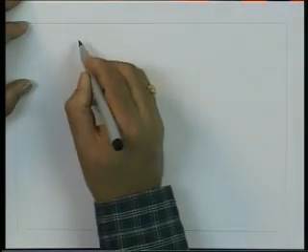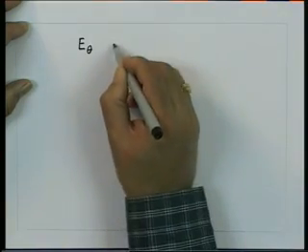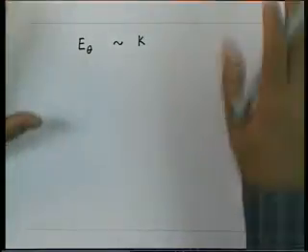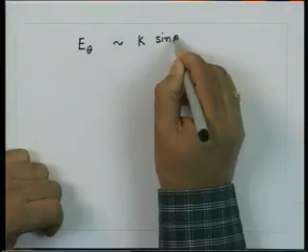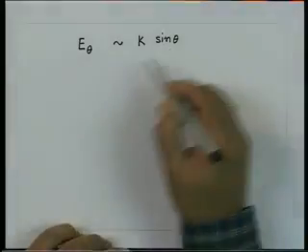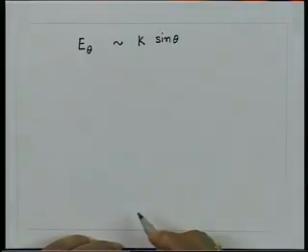So essentially we have a variation for the electric field, E theta, that varies as some constant, which includes all those factors like current and length of the dipole, the wavelength and so on, and a variation which is sine of theta. So note the variation of this field in the theta plane is sine theta.